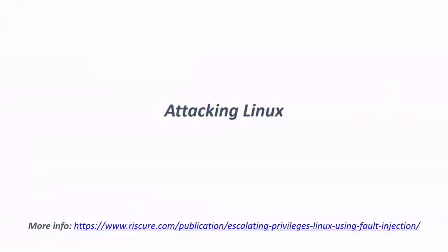What this shows is that there's some sort of relationship between the glitch voltage and the glitch length. This also provides us enough confidence that we can fix one of those parameters in order to minimize the parameter search space. And it provides enough confidence to go to the next step, and that's attacking Linux. And this is the moment I give the presenter to Christopher.